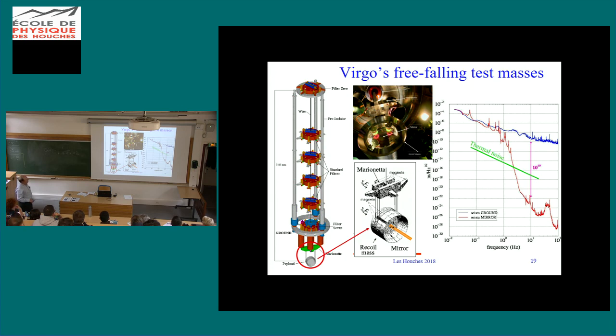So here we can see this is the low frequency resonance of the inverted pendulum, the big tower. And then here are the resonant peaks that come from the coupled modes. You don't just see the frequency of this and the frequency of this, but a normal mode, the lowest frequency of which represents all of the pendulum stages swinging together, and then various more antiphase combinations of those different stages. This is the most alternating set of motions, this peak right there. And this is fabulous, okay? This meets what I'm saying would be a good spec down to 3 hertz. It's great.